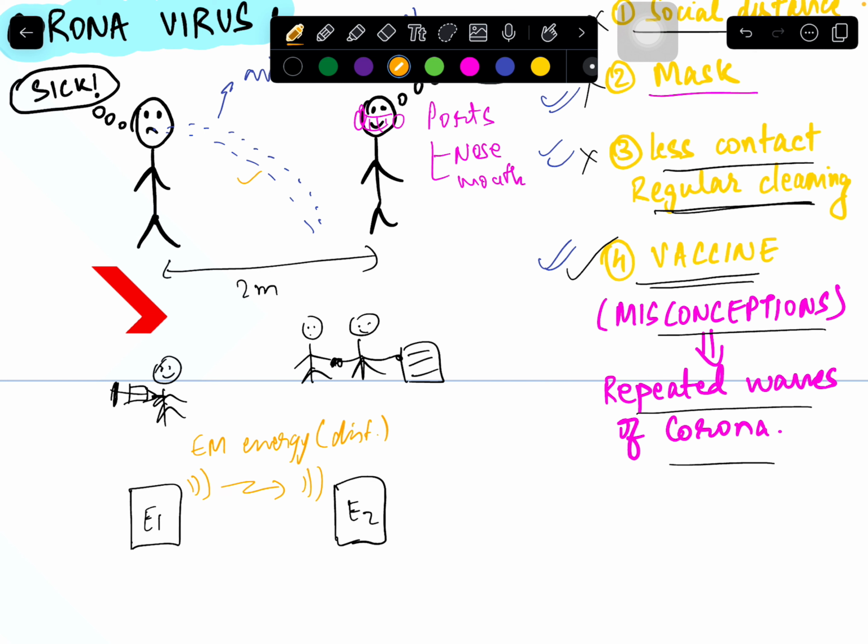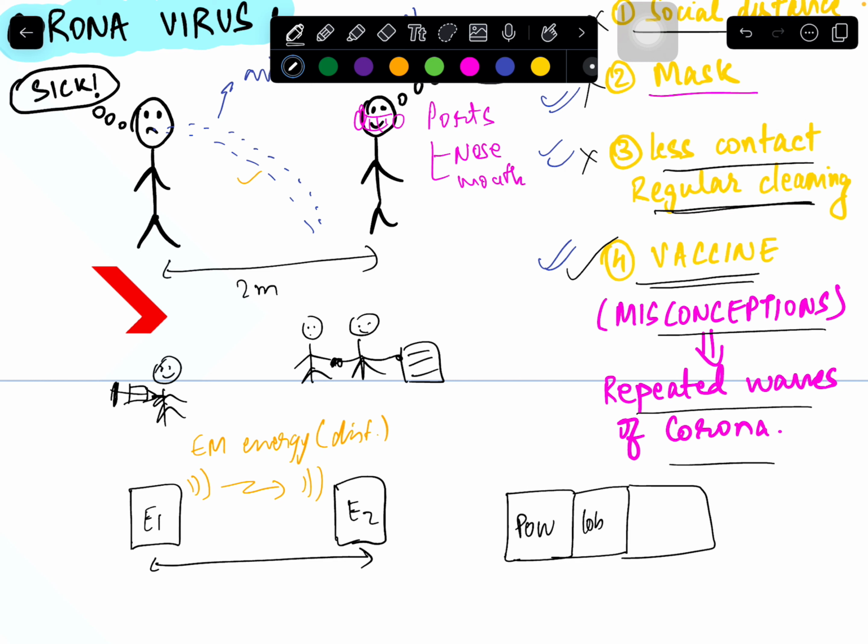So what we can do is reduce this energy value which is coming to us by doing proper distancing, like social distancing. That is why you will see EMC engineers keep telling you to please put your equipments as far away as possible. Or if you have a room layout, the power room layout is different, and make your signaling or communication room separate. Let this be a lobby, and then put a signaling room here rather than just putting the power room and signaling equipments together. Try to maintain distance if possible. So this is what is told.